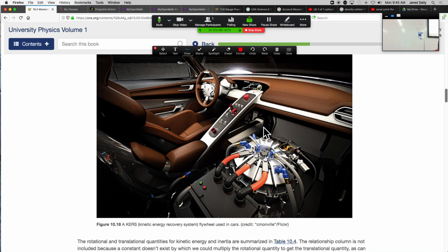So they make a wheel called a flywheel. And a flywheel is essentially like a wheel on a bicycle. It has spokes going out to the outside. And then on the outside, they put some really heavy material like lead, because that's very far away from the center, so it's going to make the highest moment of inertia possible once you spin it, right? And then you start spinning that wheel super fast.